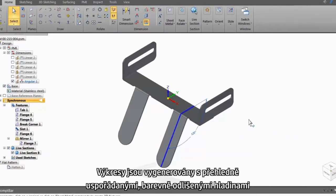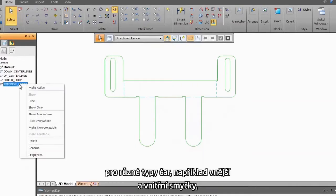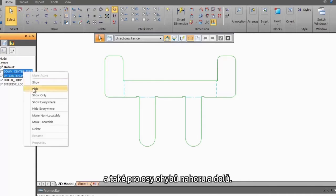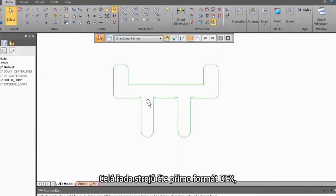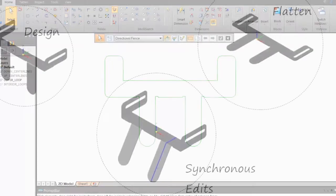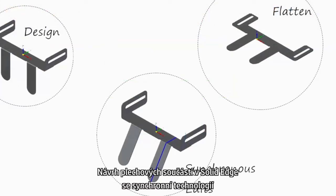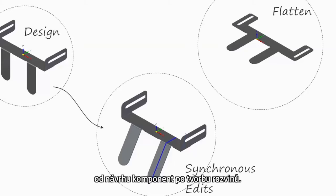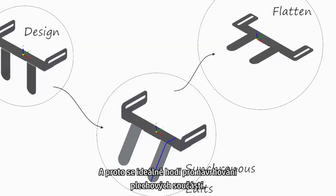The drawings are generated with neatly arranged color-coded layers for respective contours like outer and inner loops, and also for center lines of up and downward bends separately. Since many machines read DXF directly, this approach is quicker, more convenient, and less error-prone. Solid Edge sheet metal design with synchronous technology provides speed and flexibility with precise control. Solid Edge streamlines the entire sheet metal product development process, from design of sheet metal components through flat pattern development, and thus is ideally suited for sheet metal design.